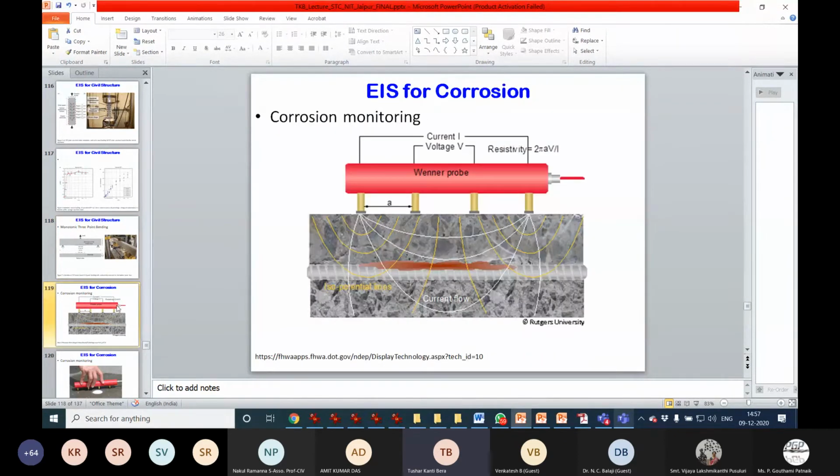Wherever we put the electrodes, that will be the domain of interest. For detecting corrosion, also underground corrosion or any corrosion within the concrete beam or structure, we can use the same 4-probe technique. With the 4-probe technique, we will get several impedance values, not images. Current is injected through the domain and passes through the material, so it carries some information. If there is no corrosion, it will have its own standard values for a particular material and structure. If we continuously monitor and record that as a standard, and after several years we see different values, there will be chances of corrosion or other defects.